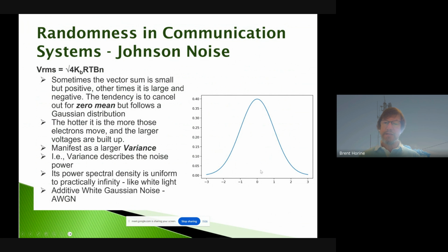And so we have a zero mean process, but the hotter your system is, or the more noise you have in the system, the broader this distribution will be, meaning there's a higher probability that you will have large excursions. So this curve will be broader, and any given excursion, denominated perhaps in voltage down here, it could be current, it could be amplitude or something like that.